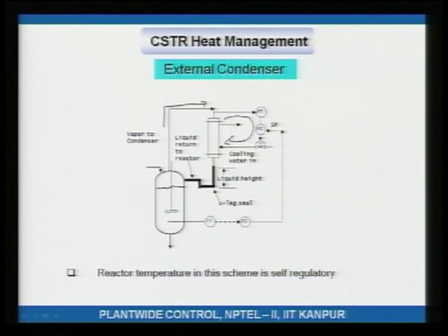How do you adjust the temperature? Well, you adjust the set point of the pressure controller. And how does this work? Well, the higher the pressure, by vapor liquid equilibrium, at a higher pressure a mixture boils at a higher temperature.